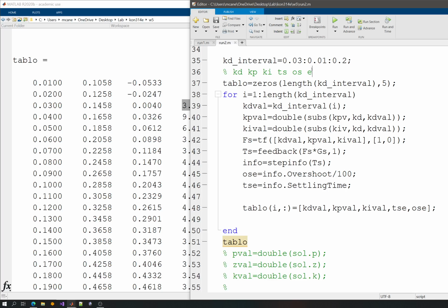I can do that if I had just one design parameter. I would just use the absolute value of the error between the settling time I was supposed to accomplish and the experimental result. I would take the difference, use the absolute value, and I might also want to convert it into percentage by dividing it by TS.